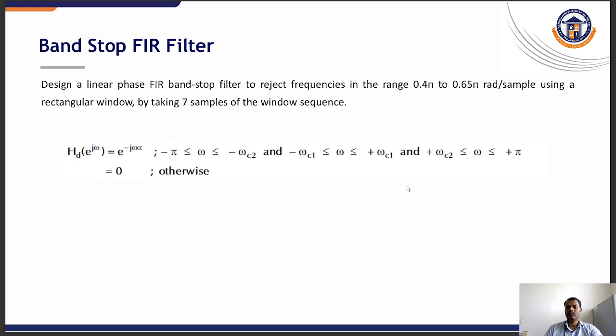This process effectively cuts the impulse response to a finite length. The choice of window function is a trade-off between a narrow main lobe in the frequency domain, which comes at the cost of higher side lobes. This means that a narrow main lobe gives a sharp transition band, and higher side lobes give more ripple in the passband and stopband.